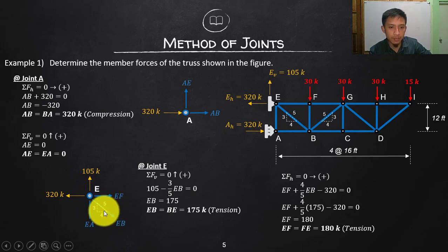If I break this down, I can include that on the summation of forces horizontal and vertical. Okay, so that is what we will be doing with inclined forces. Break this down into horizontal and vertical components. That's why we need this slope. By the way, you should know your slope triangle. Okay, where did I get this 3, 4, 5? I just reduced, of course, the dimension.